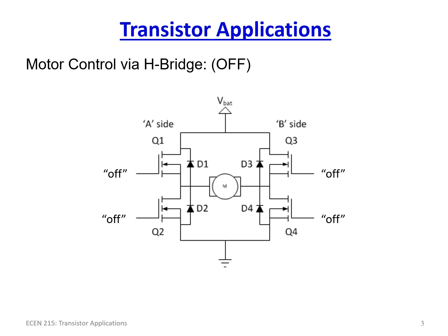So if you notice here, I have a motor, and let's just say this is the red wire or positive lead of the motor, and this is the black wire or negative lead of a DC motor. If the current is flowing from red to black this way, the motor is going to turn, let's say, clockwise. Now, if I'm able to flip this around and reverse it and flow current from black to red, or negative to positive, now the motor is going to turn in the opposite direction.